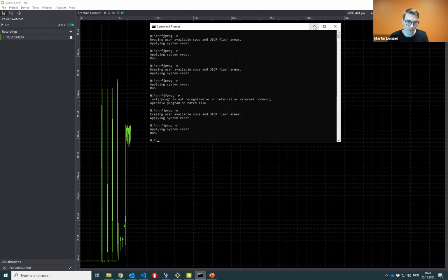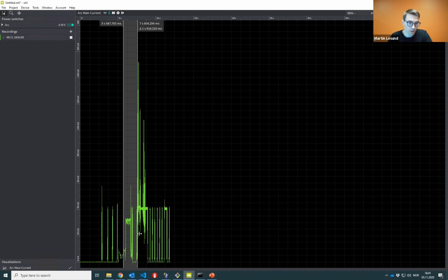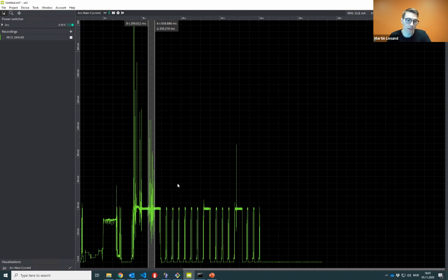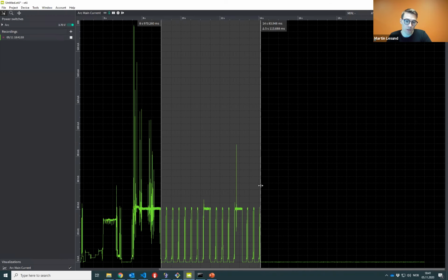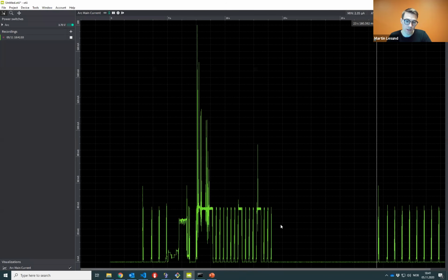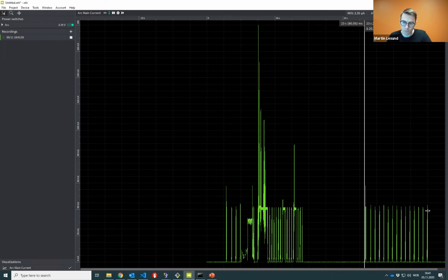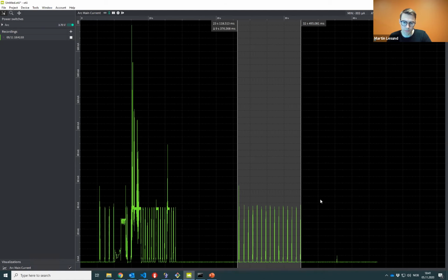So now I just restarted the device. Now we can see it connected to the network very fast and sends the data around here. So it just sends a UDP packet. And then we have this famous inactivity timer. For this network, it's around 6 seconds. And here we have the first eDRX interval going on. It's around 10 seconds, so not 20.